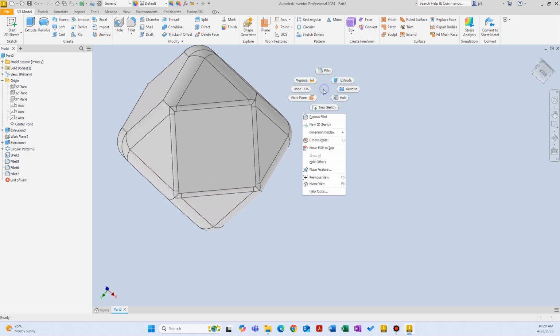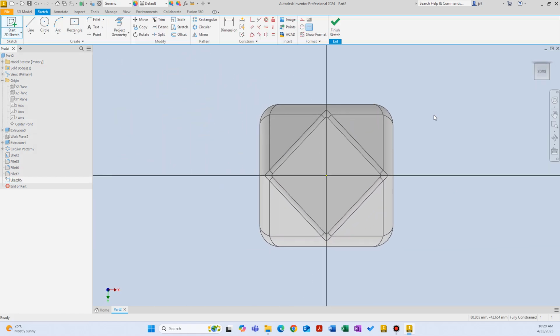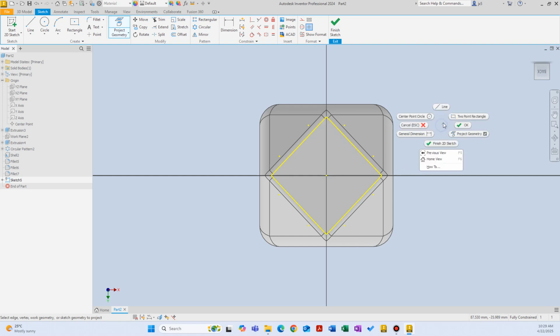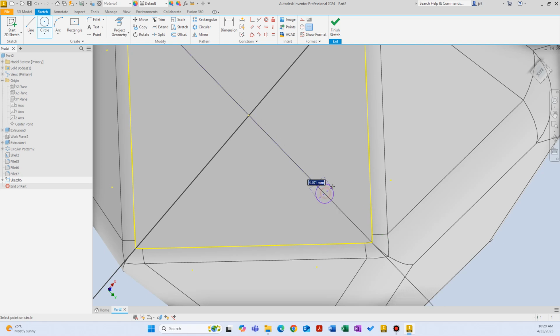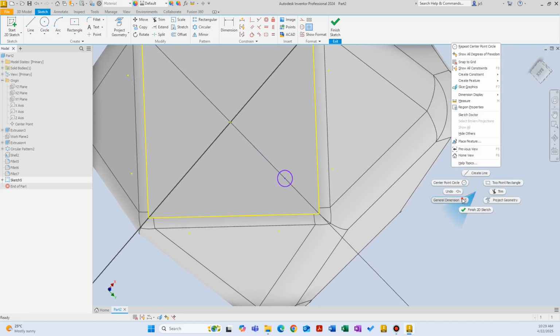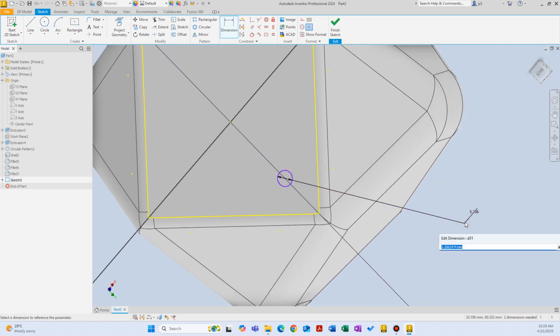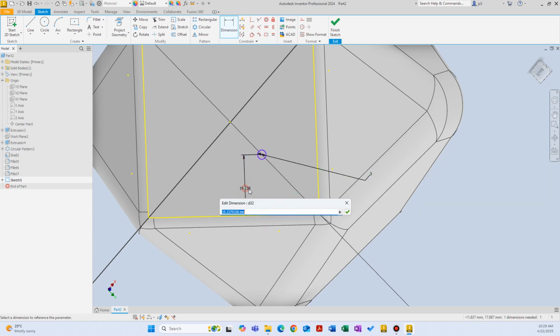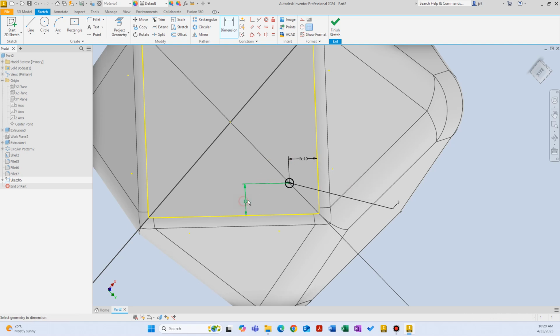But right now, this is just an exercise, and the planter pot is done. But let's add drainage holes at the bottom because these planter pots also have some drain holes at the bottom to remove the excess water. Let's look at it like this and draw a circle here and then dimension that 4 millimeters, 3 millimeters maybe. And the distance between the circle and the edge is 10 millimeters. Let's say here is also 10 millimeters.